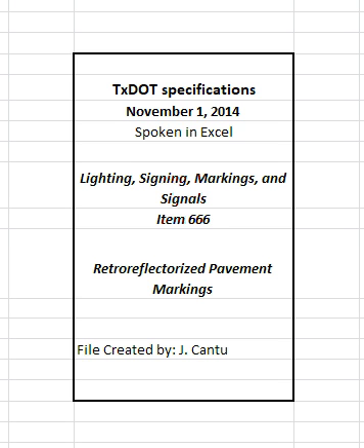A marking meets the retroreflectivity requirements if the combined average retroreflectivity measurement for a 1-mile segment meets the minimum retroreflectivity values specified, and no more than 30% of the retroreflectivity measurement values are below the minimum retroreflectivity requirement value within the 1-mile segment. The engineer may accept failing 1-mile segments if no more than 20% of the retroreflectivity measurements within that mile segment are below the minimum retroreflectivity requirement value.